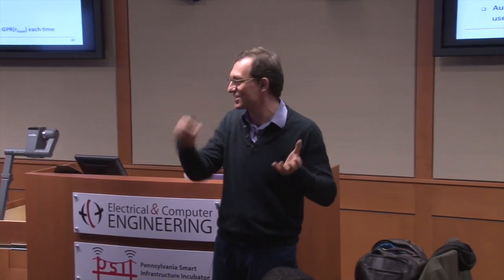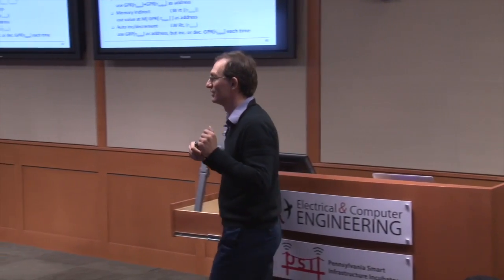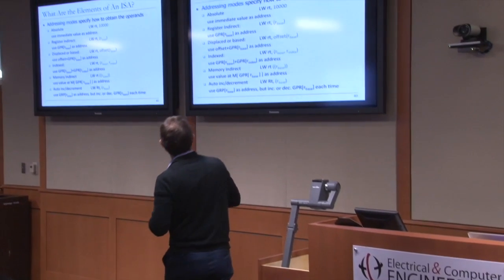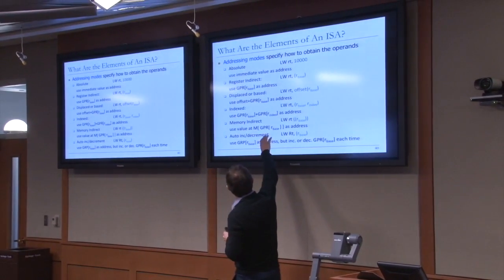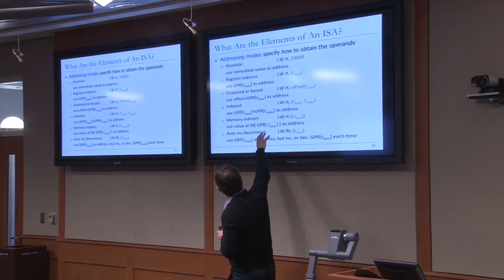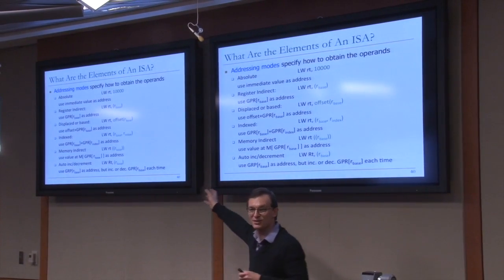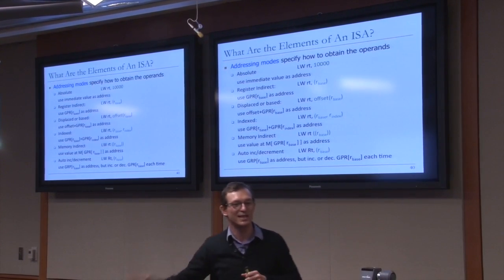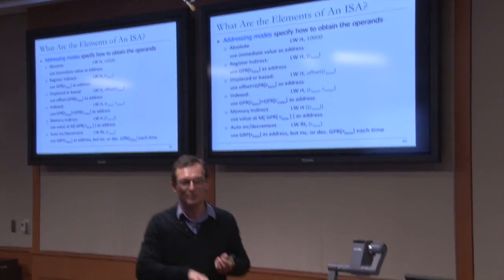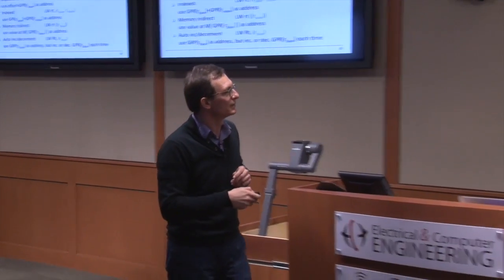the array. Right? This is nice because you don't need to now have another operation that adds 1 to the register that's your address. So again, this is a design choice that the architect makes. It reduces your code size, right? Well, what is the downside? The downside is now it increases the complexity of your load instruction, right? Because you need to do an add in addition to doing the load.